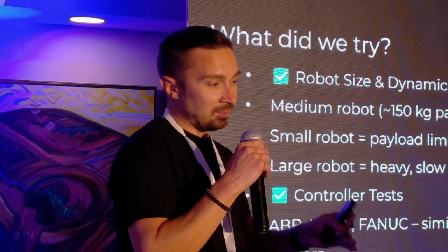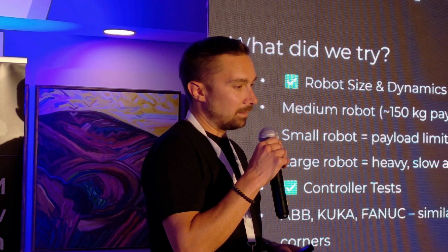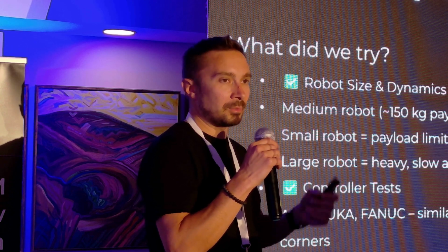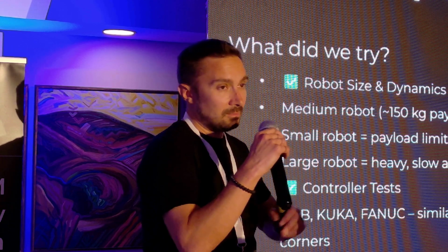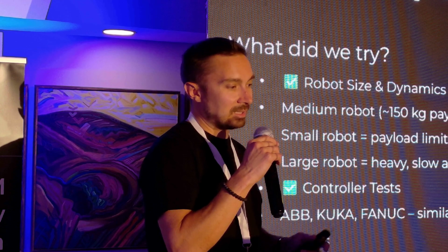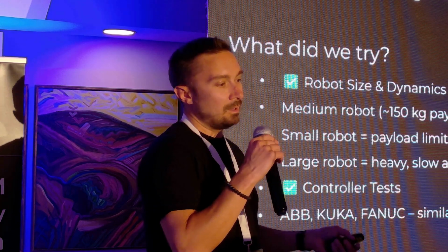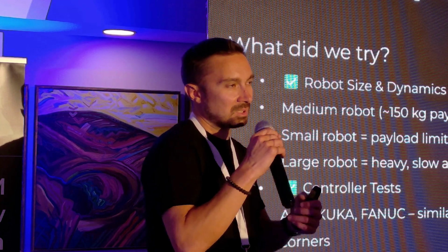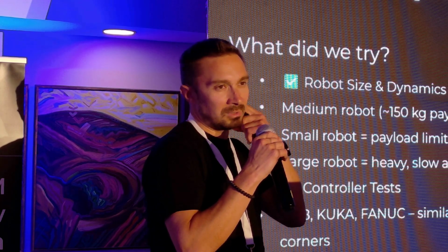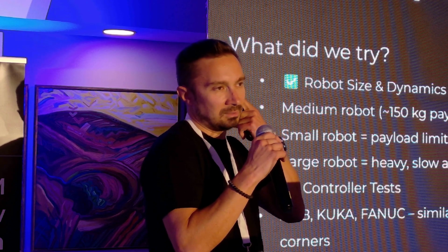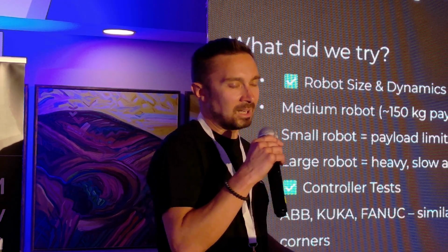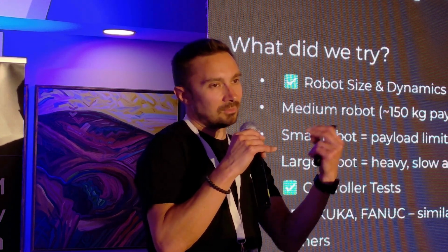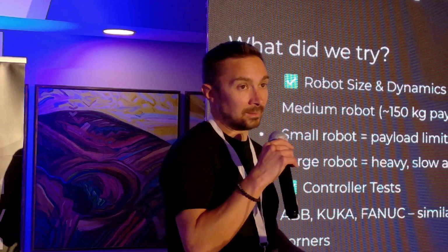Also, we tried to use different approaches to tool path generation. I mean linear interpolation, circular interpolation, also spline interpolation. And in some cases, spline works very well. In other cases, it is better to use line plus smoothing, because what we noticed is that the usual circular interpolation by the robot also has limitations. It means it brakes down speed more than, for example, if we use natural smoothing from the robot and use two lines.